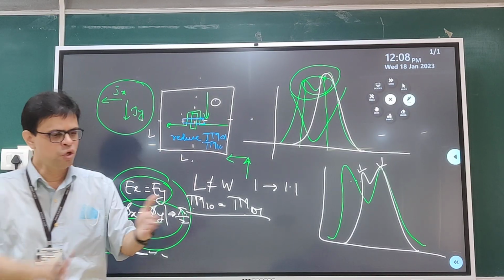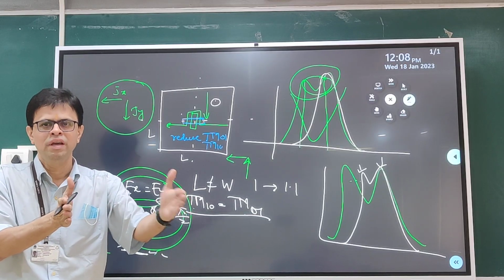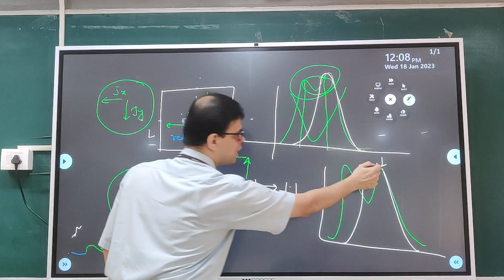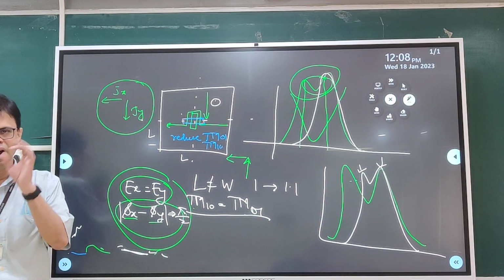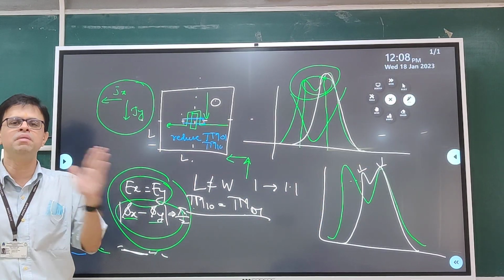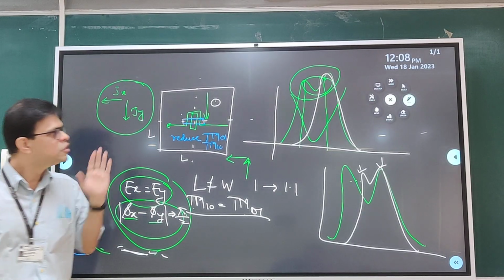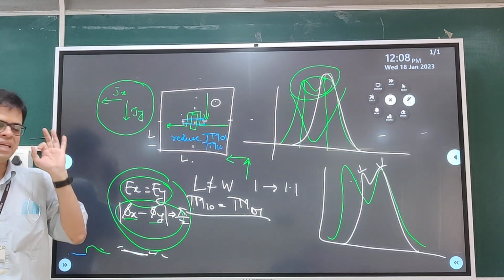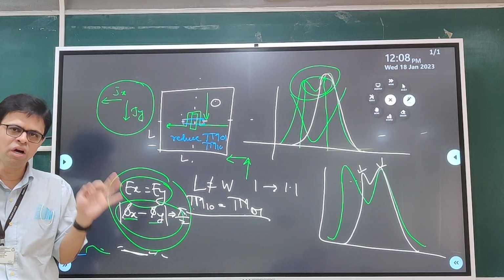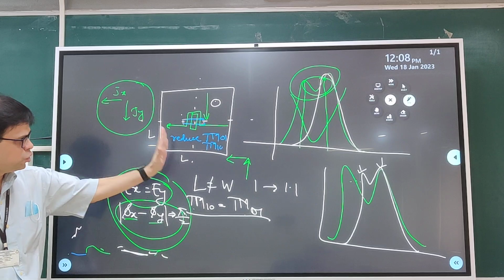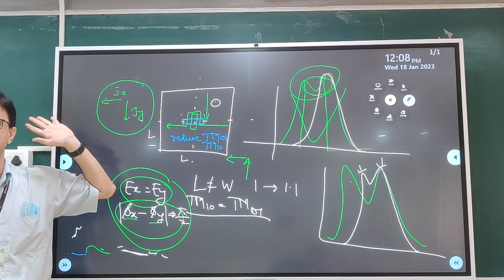In the first case, you are tuning 10 with respect to 01. In the second case, you are tuning this with respect to this, so it will reduce in its frequency. The ultimate outcome is the same. Optimum separations give me a CP response. So these are all single feed slot cut designs for circularly polarized response using a nearly square or square microstrip antenna.